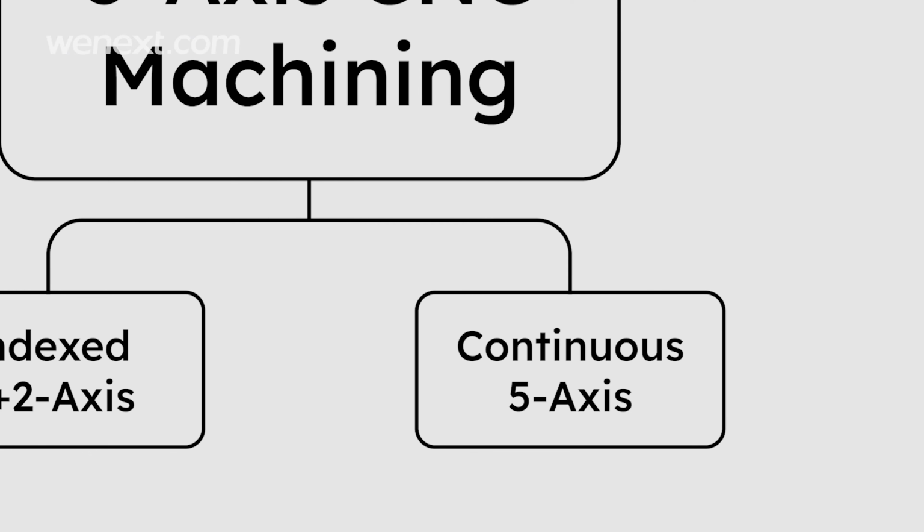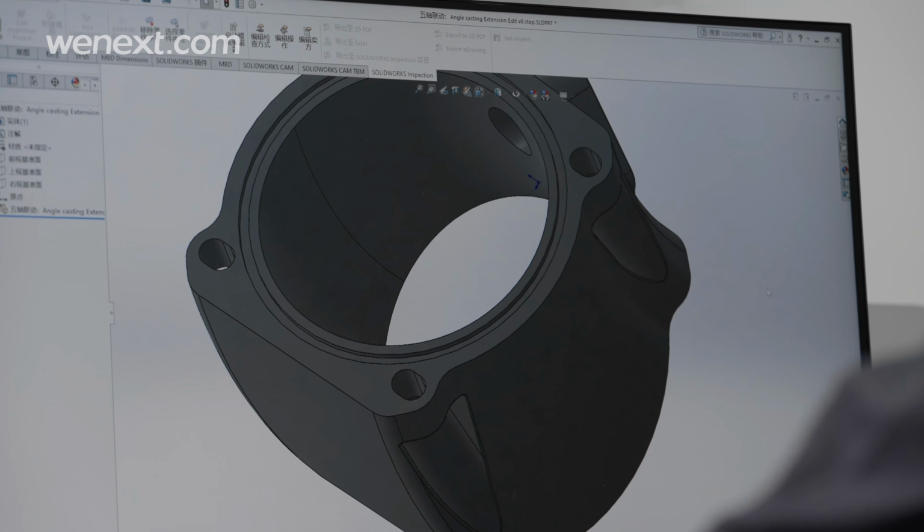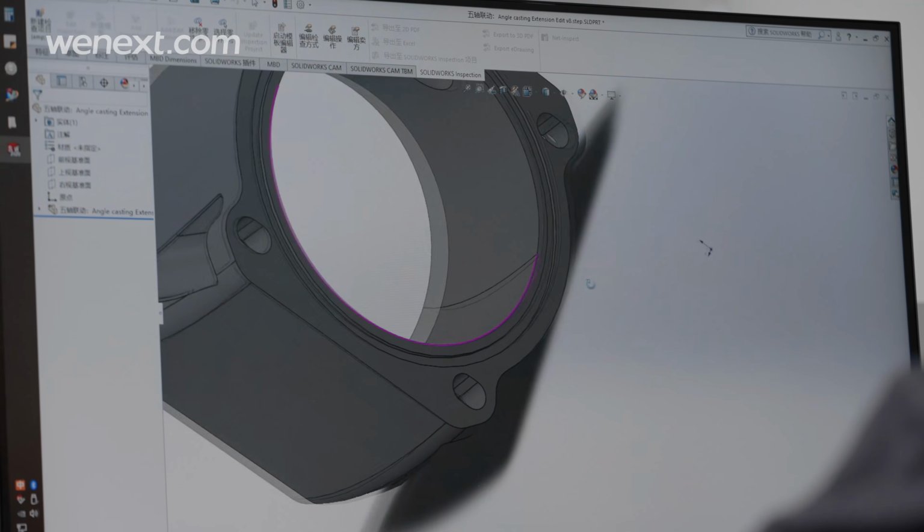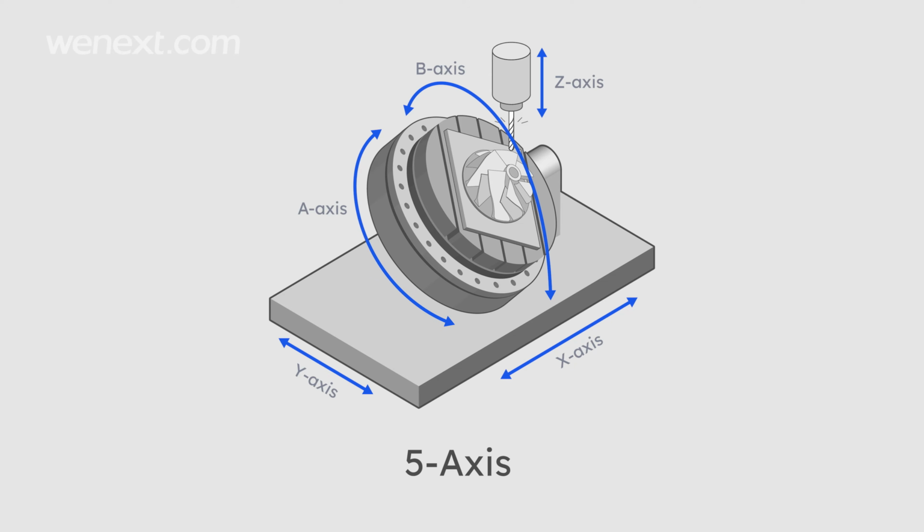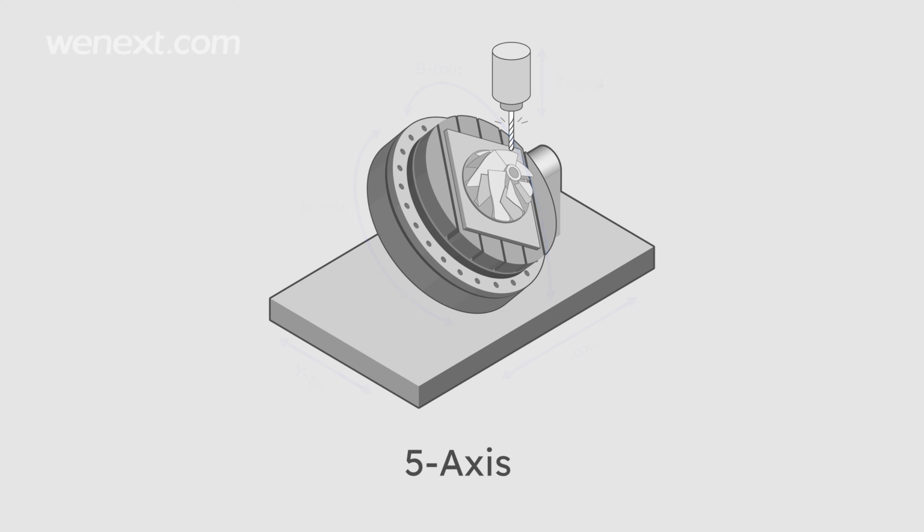Continuous 5-axis can not only cut flat compound angles, but also shape complex curved 3D surfaces. Generally, continuous 5-axis is able to produce parts that are useful for many applications. Of course, complex designs need support from professional machines and dedicated program operators, which means the cost of 5-axis will also increase accordingly. Overall, the most appropriate manufacturing method depends on the material, production volume, budget, and geometric complexity, etc.